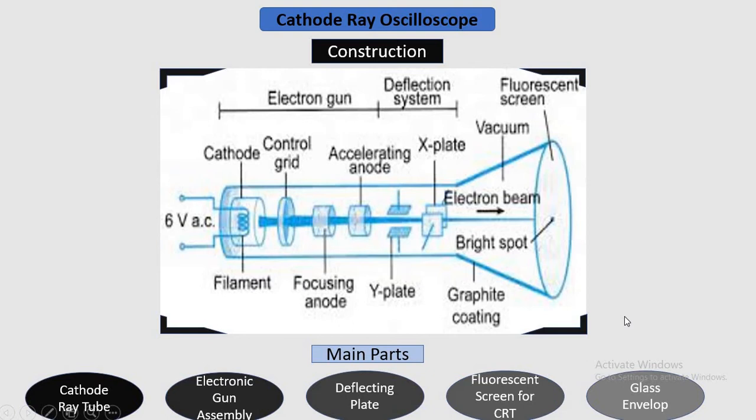After the emission of an electron from the cathode grid, it passes through the control grid. The control grid is usually a nickel cylinder centrally located, coaxial with the CRT axis. It controls the intensity of the emitted electrons from the cathode.